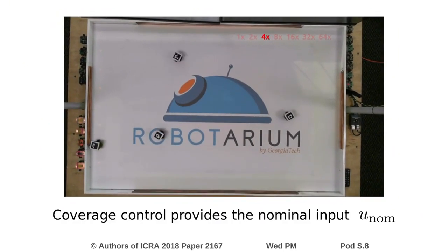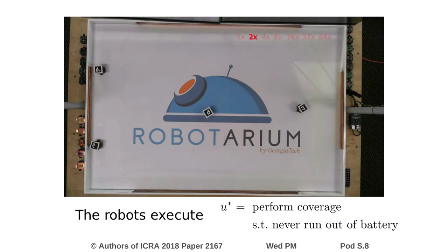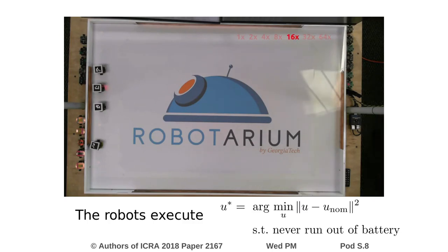A coverage control algorithm provides the nominal input u nominal, but what the robots actually execute is u star, the solution of an optimization problem. The robots execute coverage control as well as possible, provided that they don't run out of battery. Mathematically speaking, this is realized by minimizing the difference from the nominal controller such that the constraints encoded using control barrier functions are satisfied.